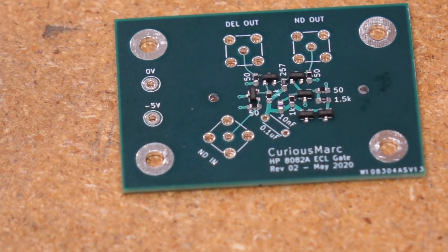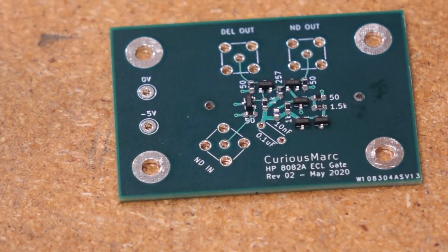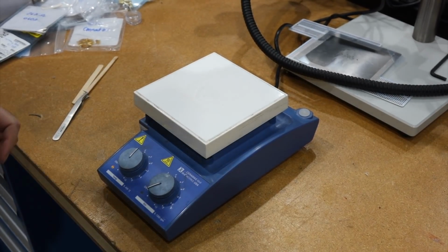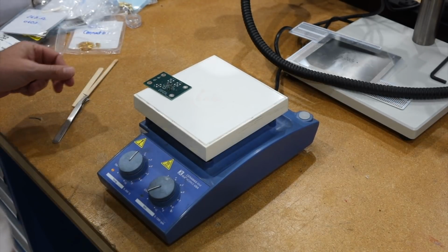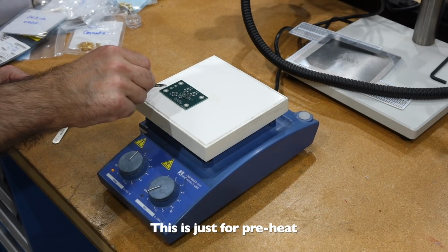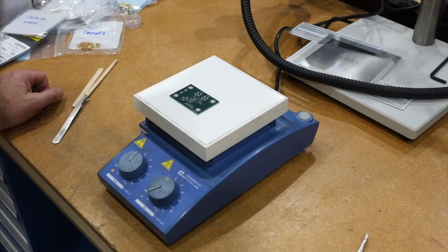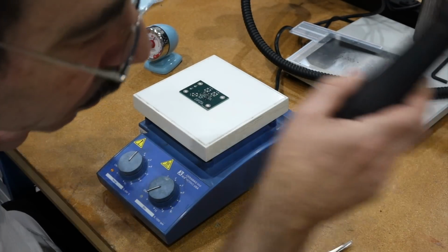So here we go, I have all my surface mount components. The only slight mistake I made is I don't have the right pattern for transistors, but it will still work. It's just the pads are a little narrow compared to where the pins are, at least for that transistor. Okay, next step, I will be using my hot plate because I have one. I don't think it's a mandatory step, but it makes it easier. And it's set at 120 degrees Celsius. It has been cooking for a couple of minutes, so it should be good to go.